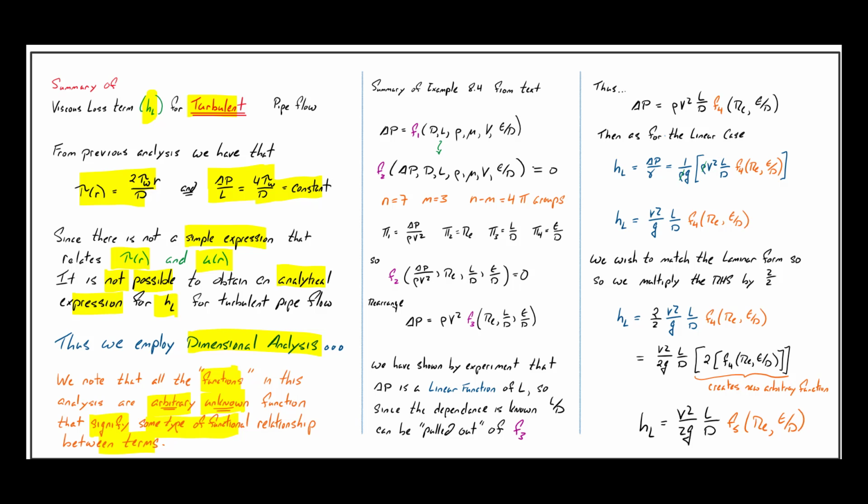So if we summarize the analysis, someone who has studied this would say that the change in pressure as fluid flows through the pipe has some relationship to the diameter, the length of the pipe, the type of fluid, the viscosity, and one term that we didn't add for laminar flow, because it's not important there, the term that describes the roughness of the pipe.